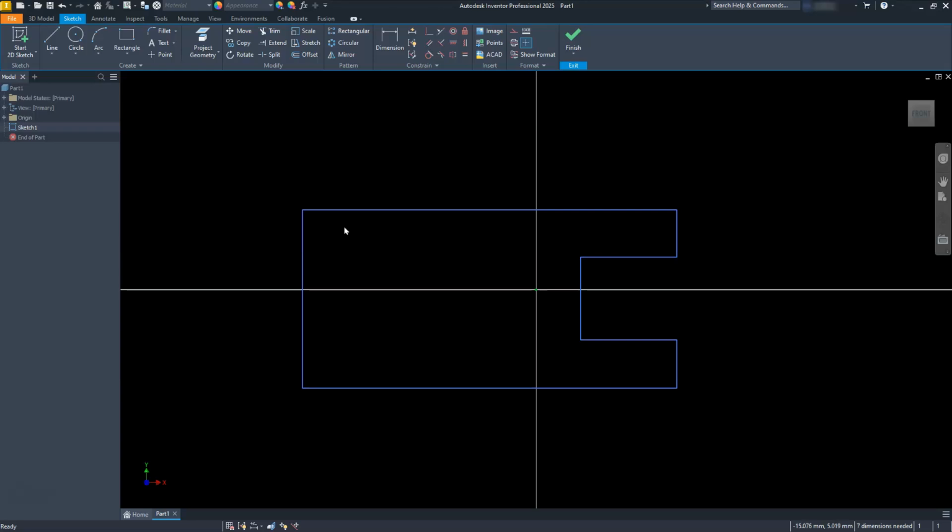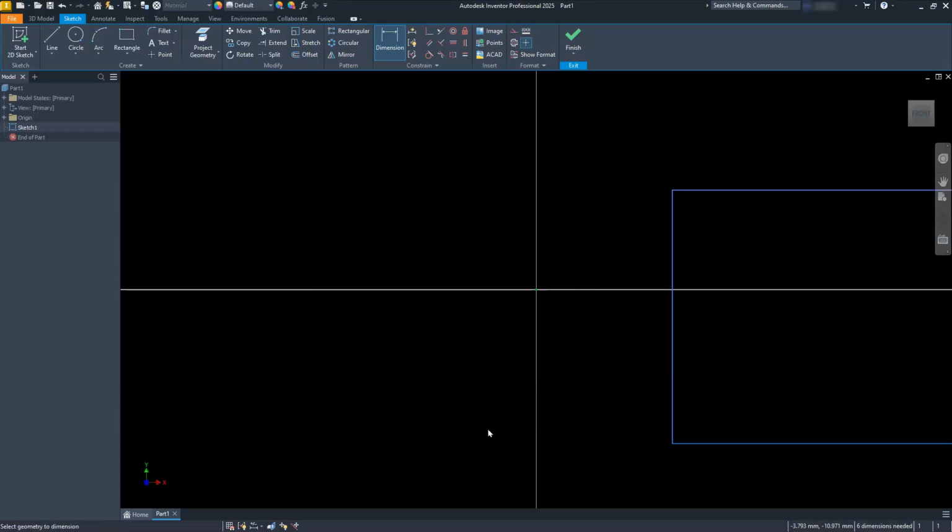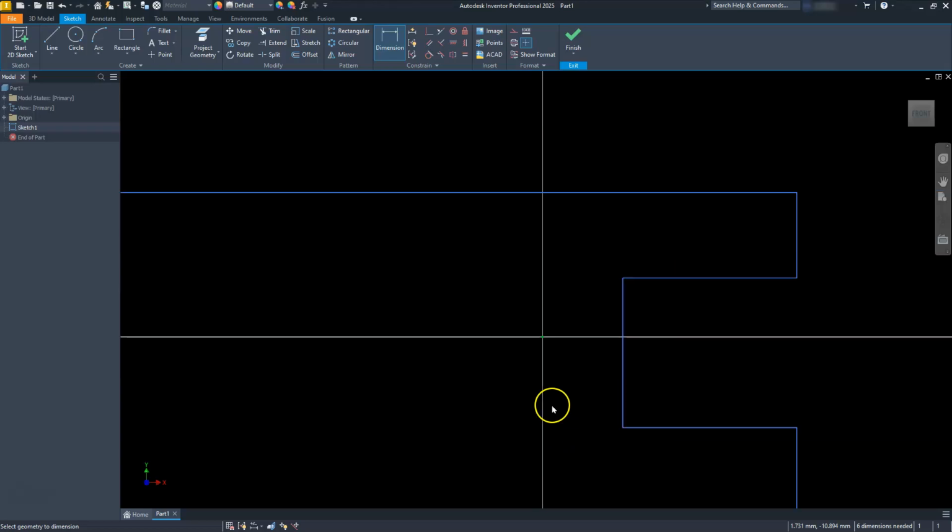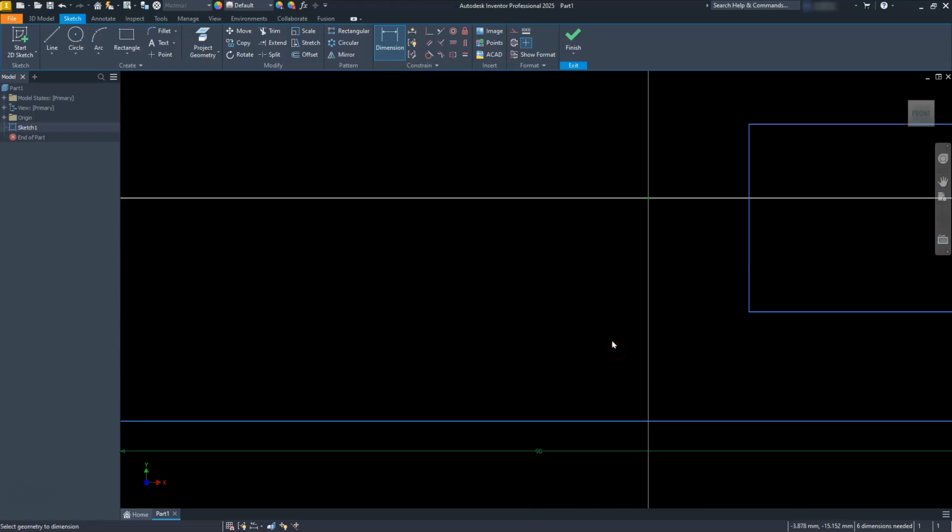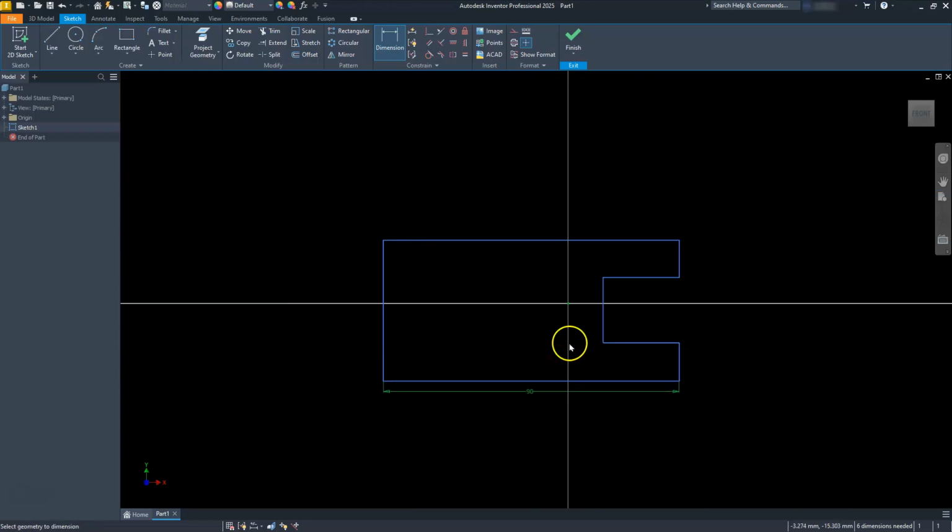The first thing I like to do is always figure out what's my longest dimension, right? So referring back to that drawing there, that dimension was 90. So I'm just going to click here, type in 90. And remember, your first dimension you put on is going to be your scale dimension. So you can see that it did indeed scale my whole shape up to fit this 90 on the inside of this. Let's go ahead and put a few more dimensions on here.